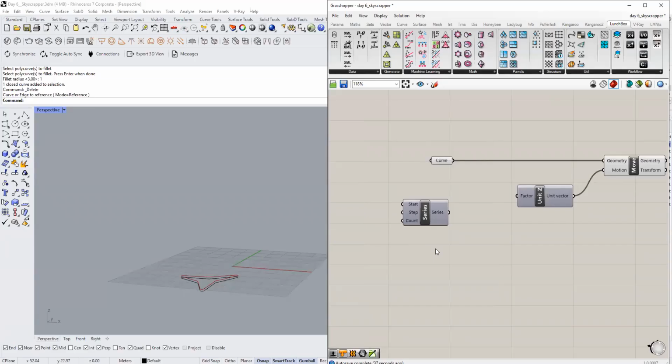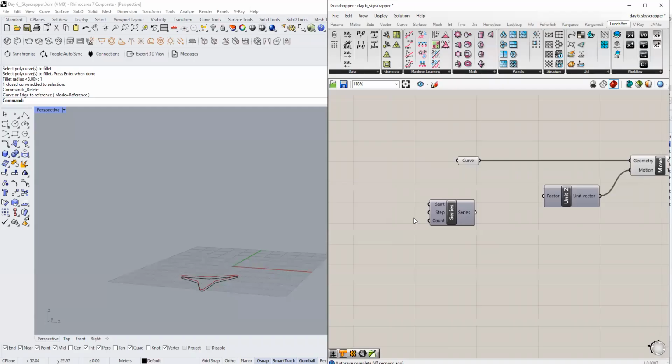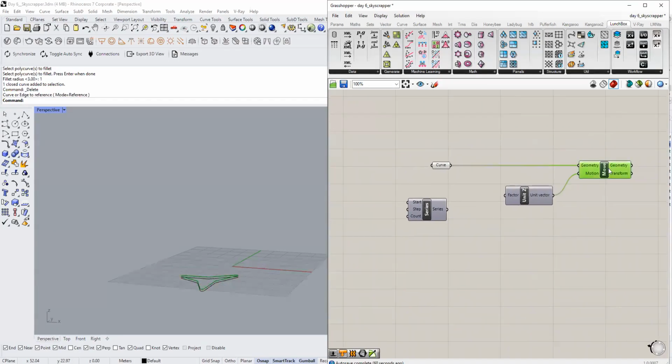Zero is okay, right? I could give it as 0. Essentially, starting value refers to the position of where the first floor plate has to be. If you want it at the ground level, give it 0. If you want it at a plinth level, give the height of the plinth, maybe 0.3, 0.6, depending on the height of the plinth. You can specify that to be the start value. So start refers to where the first floor plate has to be positioned.